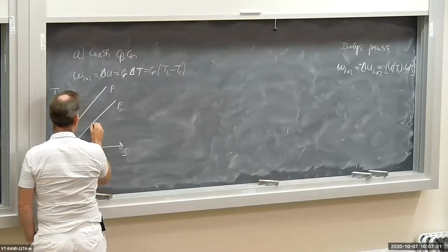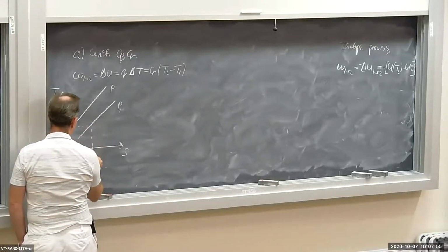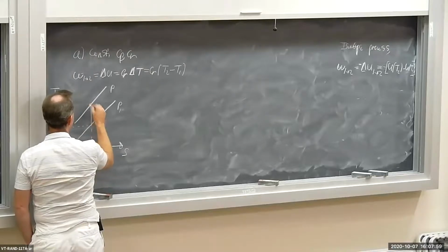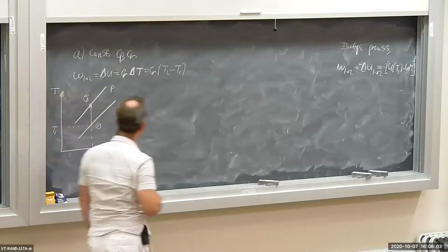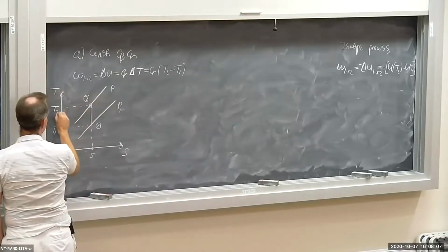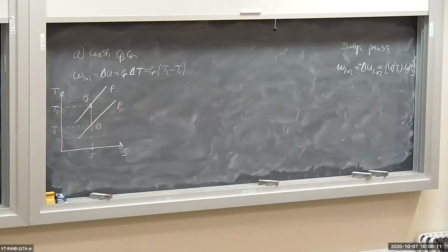We start off at a temperature T1, and we have, of course, a certain S. And the idea is we're going to go vertically up from state 1 to state 2. We're going to end up at a temperature T2, of course. Isentropic process from temperature T1 to T2. That's what the process looks like on the TS diagram.